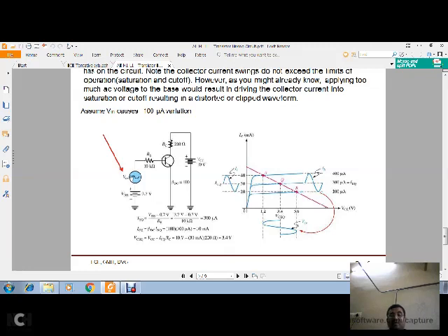So this AC signal varies on the DC input signal, right? This is the Q point. This is where I am going to apply my AC signal. This is called ib, small suffix b. This current is due to this analog input voltage. And capital IB is only for biasing, in order to fix the Q point.